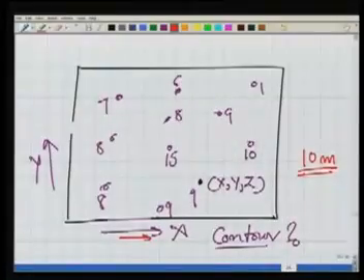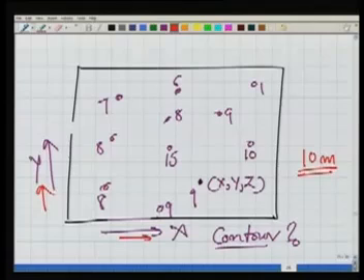For each point, we measured its x and y, or the planimetric position, as well as its RL. So the data is with me. The moment I write x and y and fix a point here, I'm fixing it because I know its x and y. This 8 indicates the RL of the point.